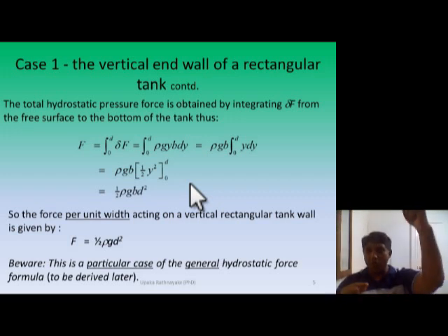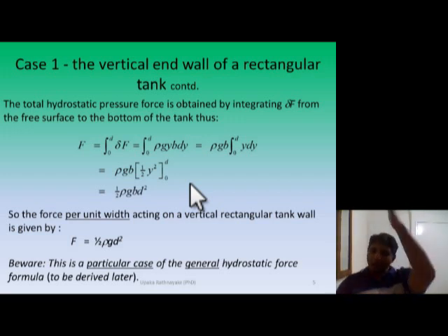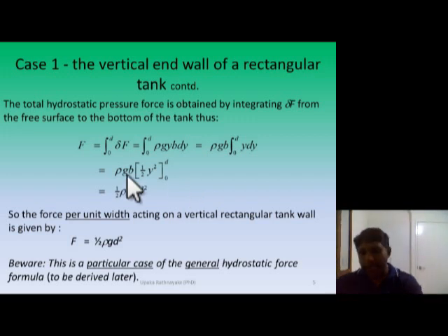So we have 0 to rho g d, that's the triangular. So the uniform is half rho g d applied on the total area b d. So our induced force is half rho g d into b d, ending up with the same answer.